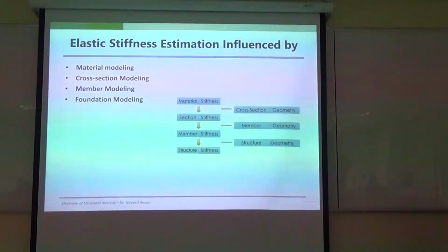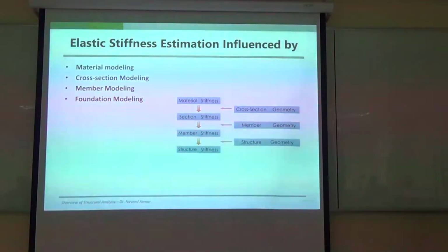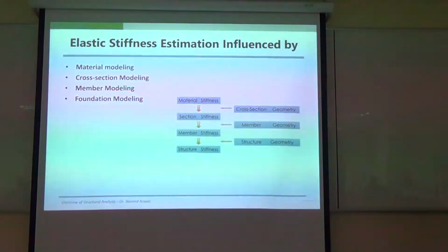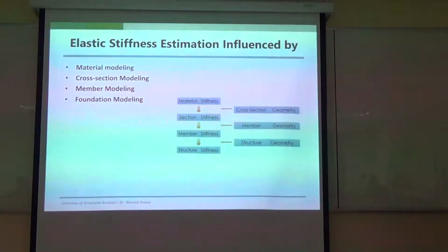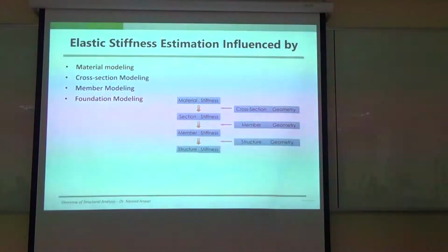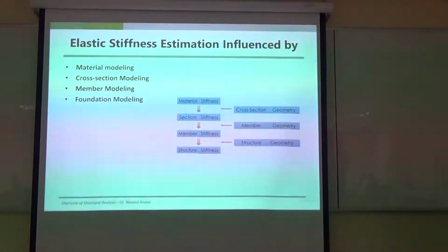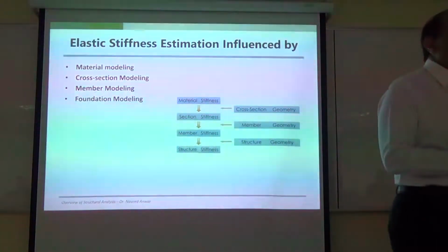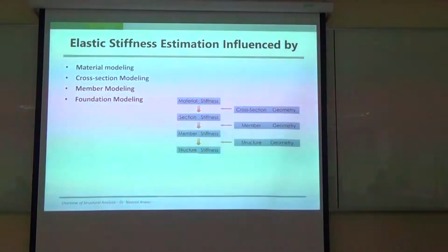Yes. In many ways, if it is damaged, stiffness will become smaller. But at the same time, concrete strength is gained. So there is a mixed thing. So stiffness at any given time is also not well known, and it depends how you model things and how you calculate stiffness, how much reinforcement is there. So stiffness estimation is very important, because if you estimate the stiffness incorrectly, natural period will be wrong again.